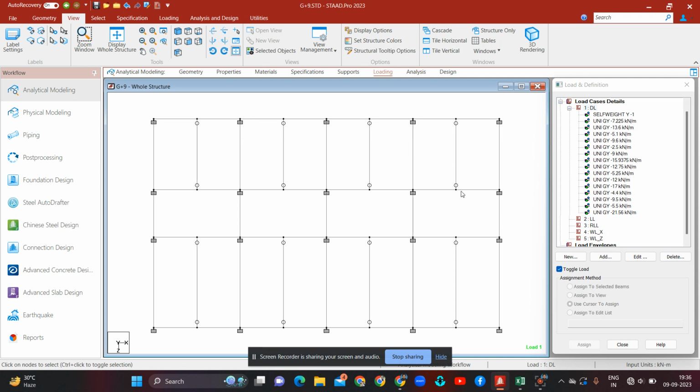Just for the floor load, I will specify some range, from the x direction from 0 to some distance, z direction some distance to some distance, and y direction as well. By that range it will be assigned.